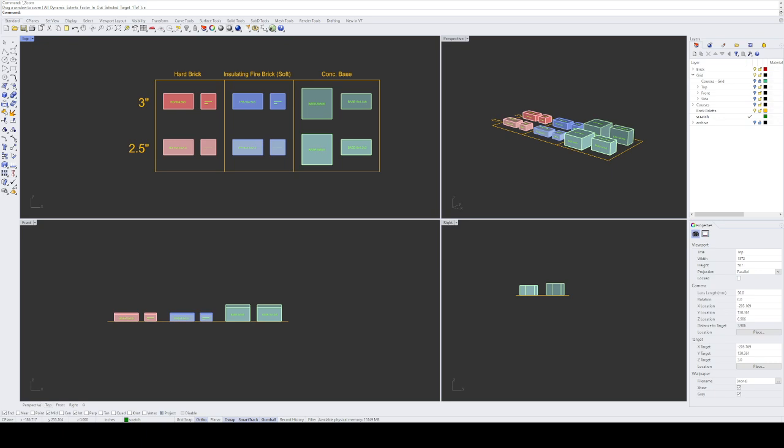Actually, before I do that, the other thing to look at over here is the layers palette and the properties palette. These will be more important later, but for now, I think it's just understand that every object sits on a layer, which is useful because right now, all this stuff is on the layer that I call brick palette. So if I turn those off, it hides it. And that's what the little light bulb does. If I click the lock button, it means that you can't select the things on that layer anymore or manipulate them. Unlock it.